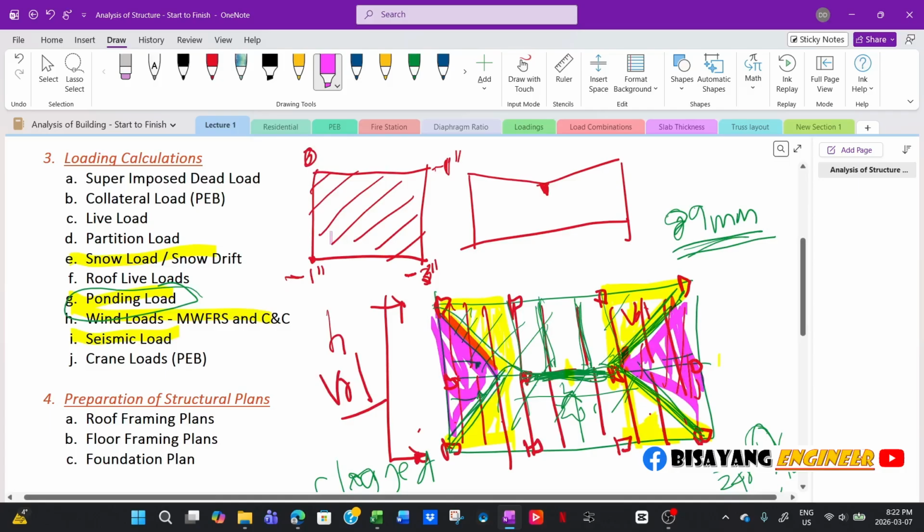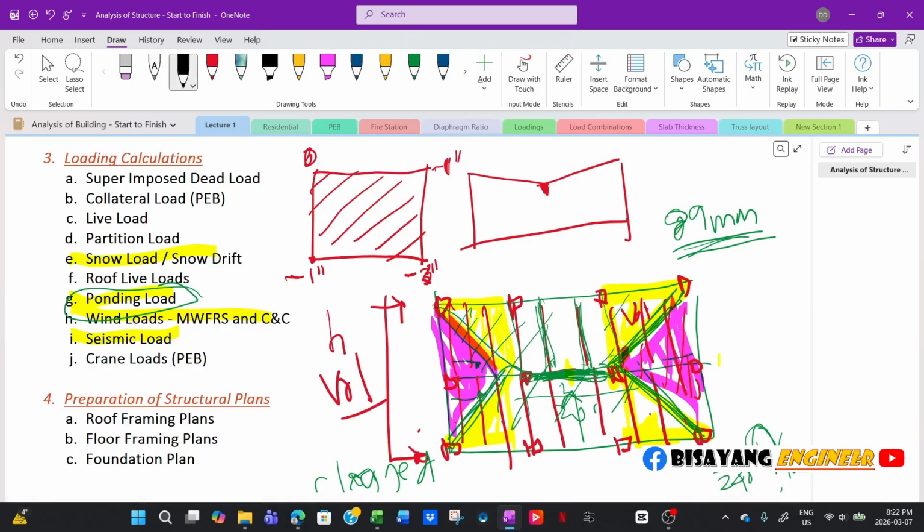So you have three sides because this is the same elevation because it's sloping that way, right? So you have whatever, this is 0, this is 0, this is 0, and this is what, 6. In this particular example, this is 6. So this is minus 6. So 0 plus 6 plus 0 is 6, divided by 3 is 2. So the average height is 2 times the area of the triangle. So that's your volume. Say volume 2.